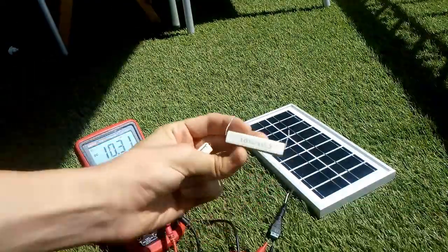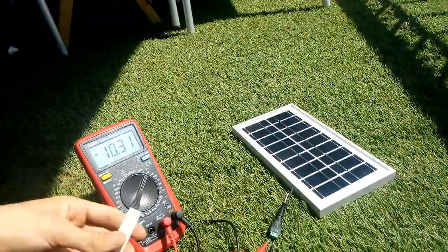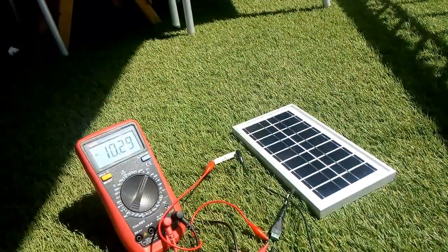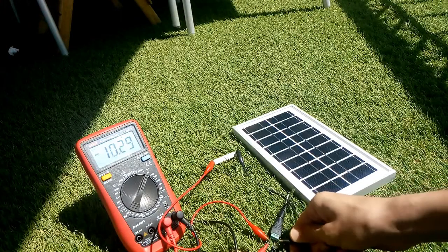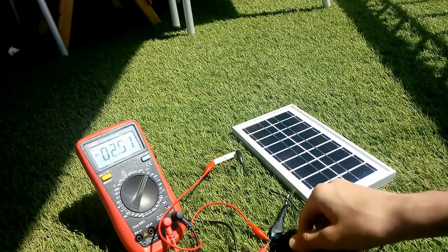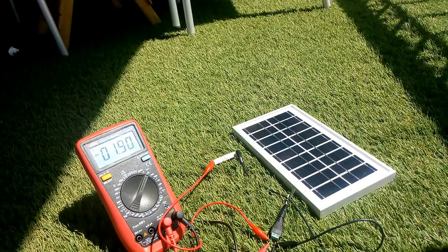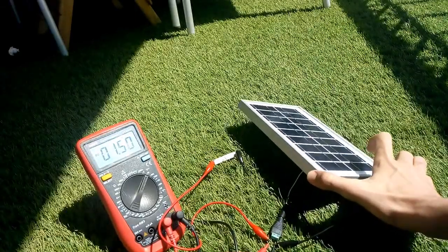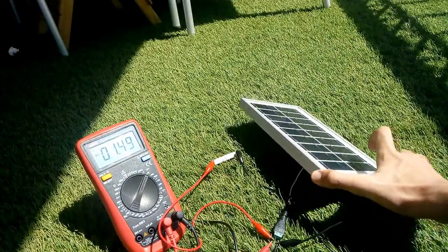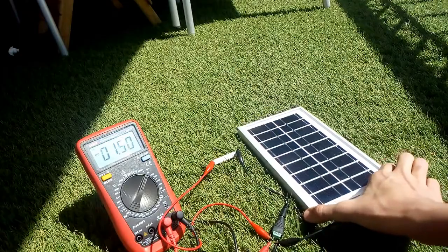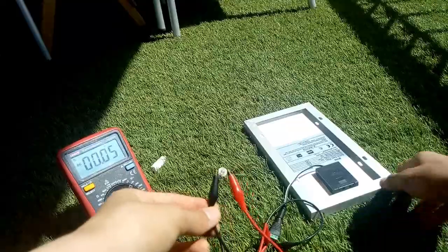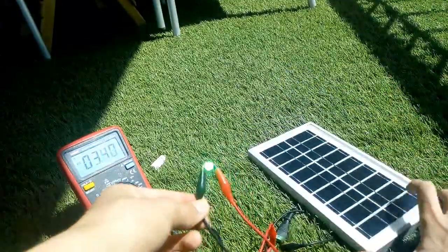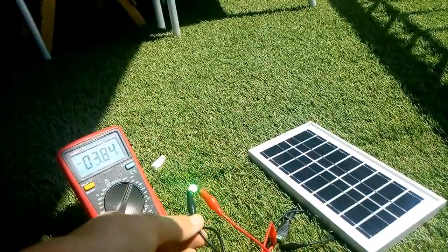And this is a power resistor I will use to show you that also when I connect a big load like this, so it's typically 10 ohms, you can see that the voltage drops to 2 volts. So it cannot keep up with this high current draw. So you probably have to just charge a battery with the solar cell, not connect directly. So this is a wrong thing to do, but I just do it for fun.